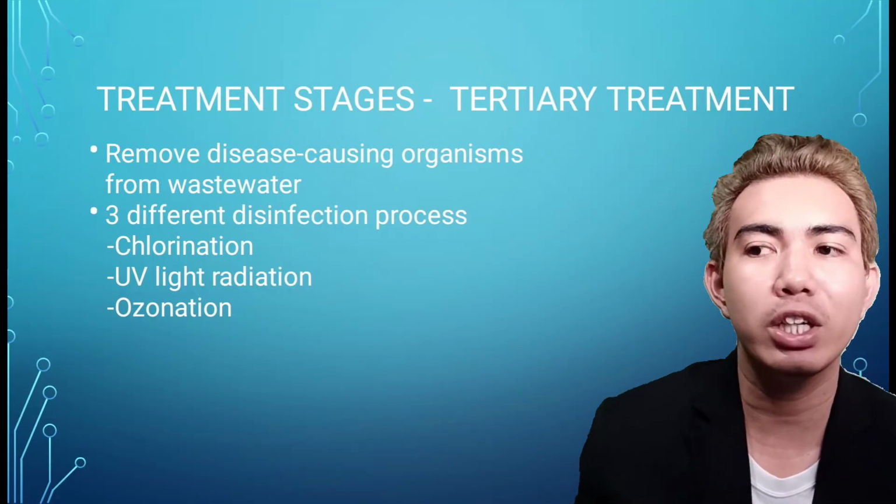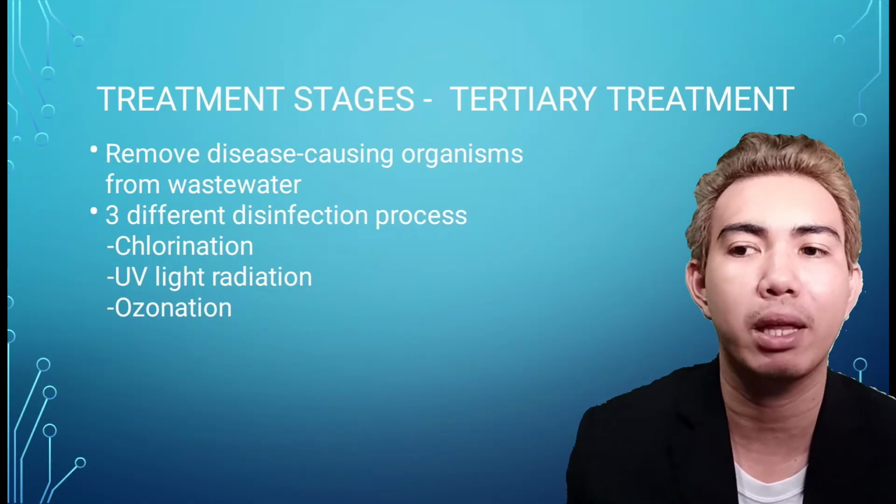Next, the wastewater pipes to the secondary clarifiers. The microorganisms are separated or returned back to the aeration tank. Revolving arms simultaneously withdraw the concentrated microbes from the bottom and skim the foam from the top. And lastly, we have the treatment stage, tertiary treatment.